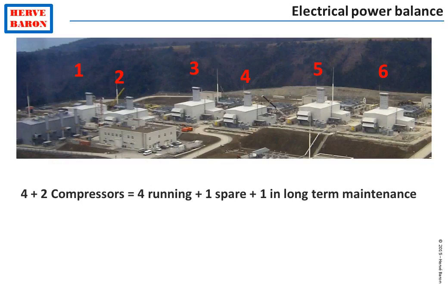Indeed, when one compressor has to be taken out of service for maintenance, then to ensure that the plant duty is still met, operations need to put a 5th compressor online before the compressor is taken out for maintenance. Therefore, at this point of time, 5 compressors will be running. So 5 times the consumption of one compressor is the maximum power consumption of the plant.